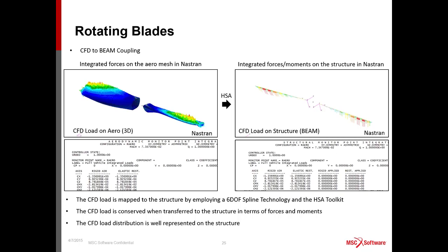Okay, and you can look at the aerodynamic integrated monitor point, and after having performed the HSA, we were able to get the same integrated load on the beam model. Okay, I just show you the forces, but you have even the moments there. So if you look at the structural monitor point and the aerodynamic monitor point, you have exactly the same load. Okay, so this is exactly what I meant before. The structural model can be beam even if the aerodynamic model is three-dimensional.